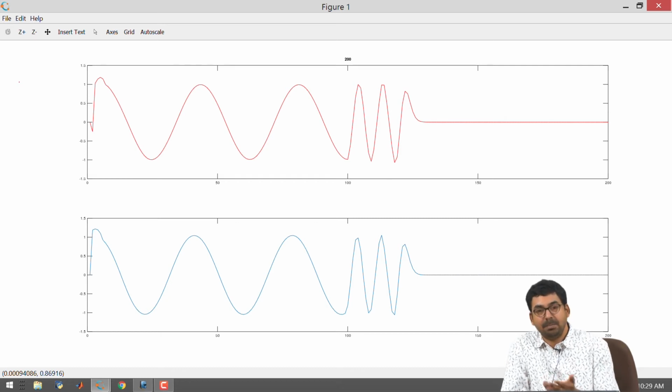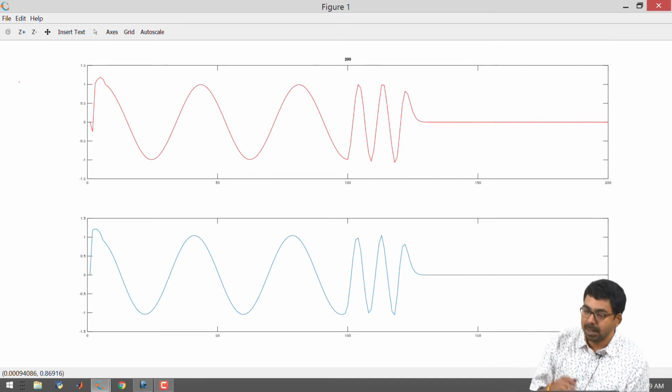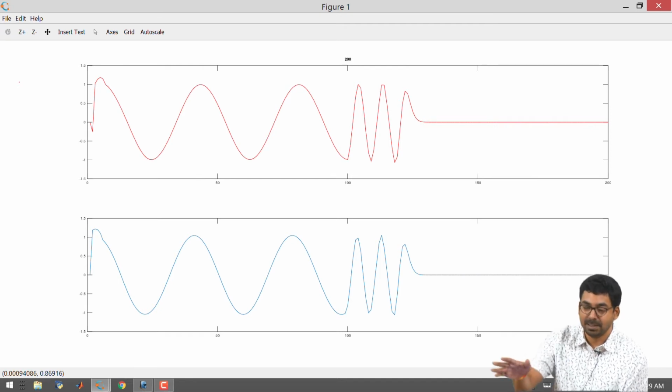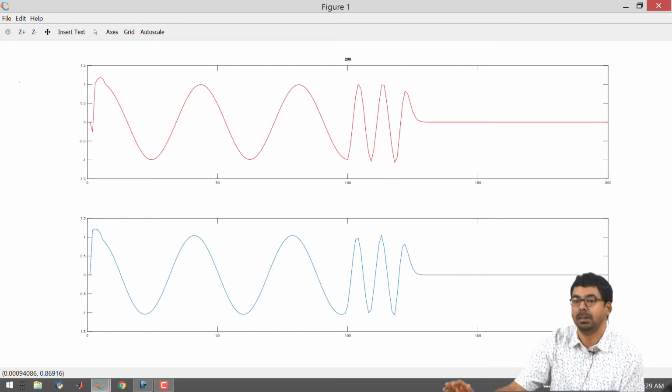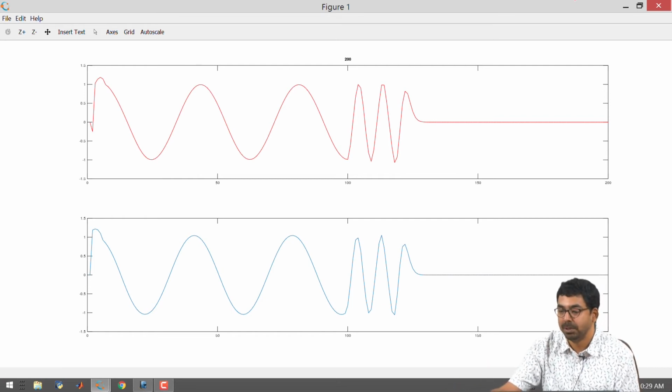As you change the medium from one to another, or the characteristic impedance from one to another, the way you sample your sinusoid will change. Those are minor details, but L and C in this right hand side section above 1 will work for the simulation condition that we have chosen. Anything below 1 will give you an out of bounds error.